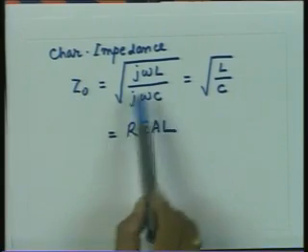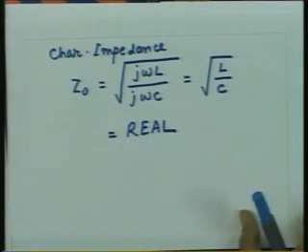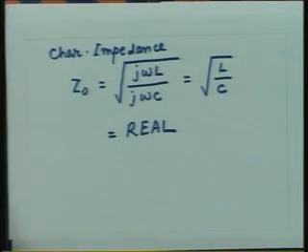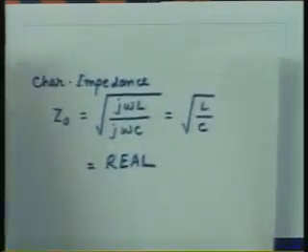Once we get the feeling for the lossless case, one can go to the more realistic lines where the losses are small, and then ask how much these parameters, the beta or the propagation constant gamma and the Z naught, deviate when the losses are relaxed. They are not ideally 0, but they are small. So, one can now define a more practical line, which we call the low loss transmission line.